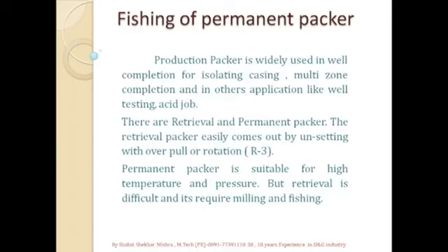In some packers, if we cut the mandrel, then the slips of the packer will retract and we can take out the packer. In some cases, we have to mill out the slips of the packer so that it can be pushed down in the well, or if we want, we can fish it out also.